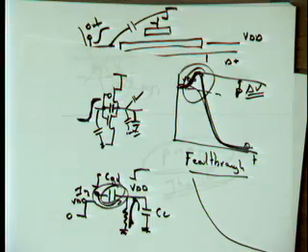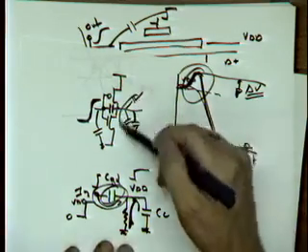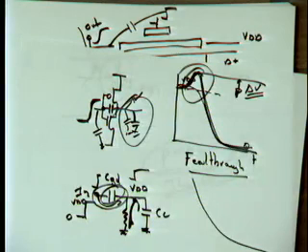The reason why you see it in SPICE is because you didn't make your CL big enough. If you make your CL big enough, you won't see this effect. It gets a lot smaller, and you maybe get 50 millivolts or 100 millivolts or something like that. But that's not bad, as long as it's not 600 millivolts. When you get to 600 millivolts, you run into trouble. Okay? Clear? So that's the effect of feed-through.